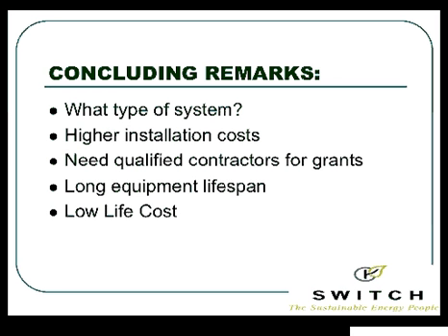Rick? I hear a lot of talk about the high efficiency air source heat pumps. Do you see that those are starting to compete with the high cost of ground source? Well, air source heat pumps have become a lot more efficient as a result of new technologies, and those technologies being variable speed compressors, variable speed fans, and better control systems on them in terms of defrosting them.